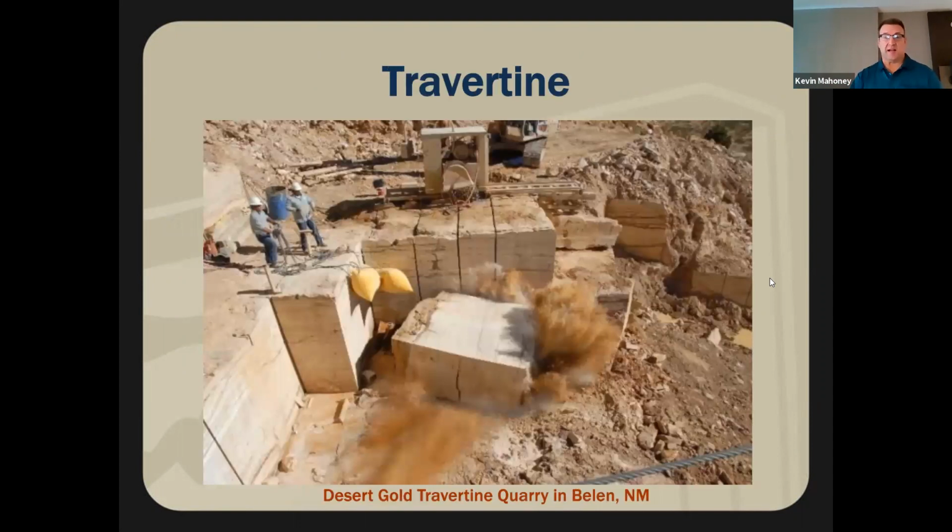This was a travertine block that we looked at before with the airbags. We can see here that the split coming across the stone with the grains, because it's sedimentary-like, broke, but it also broke down through there as well. The travertine is stronger one way than the other. Not all rocks are that way. I'm going to throw a term out there: anisotropic, which means it's stronger one way than it is the other. So important. We'll talk a little bit more in depth about that.